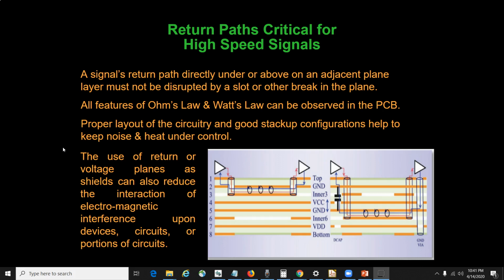When various components are separated into different enclosures, the shielding also prevents interference between components. This worked in the past with slow signals. However, with fast signal switching speeds, this method tends to just create antennas out of the intended shield. But if you're working with slow signals, then you can use ground shielding.